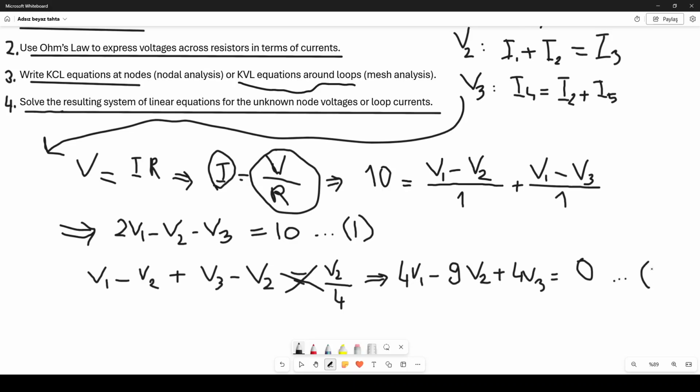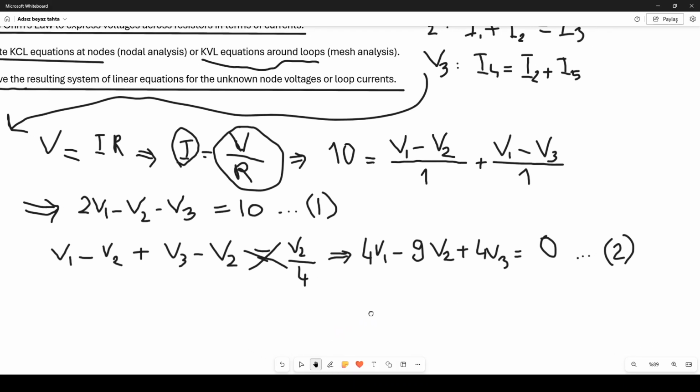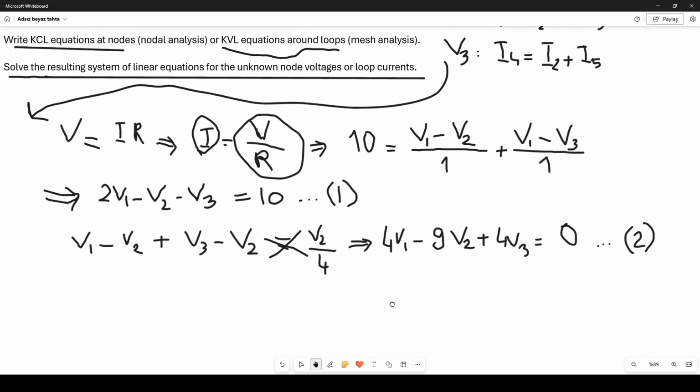And again, guys, if you notice that we again reach an equation where the only unknown variables are the voltage values as required, because we will be trying to find the voltage values, right? That's why I use first Kirchhoff's current law and then Ohm's law and define the current values in terms of voltage values, which are the only unknown variables here. And we have the second equation. Now, there's only one thing left. So if we are able to write the third node in equation form, then we have our system.